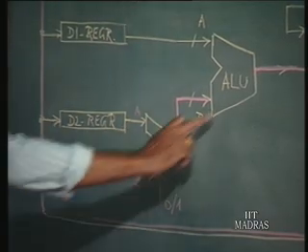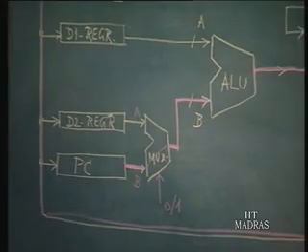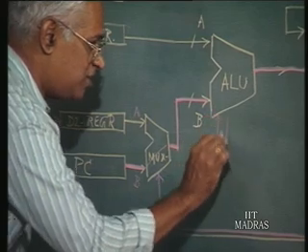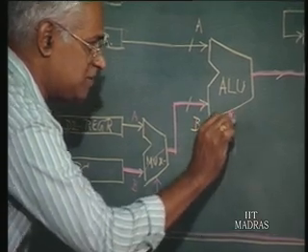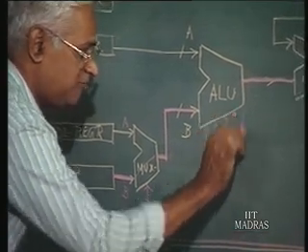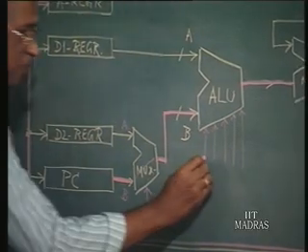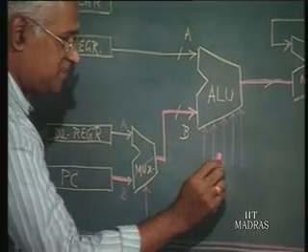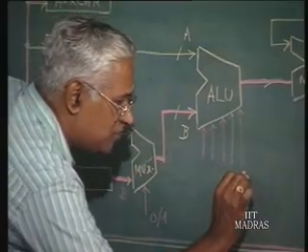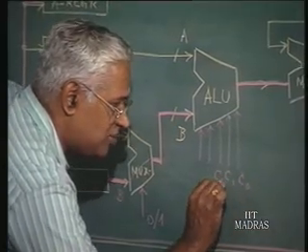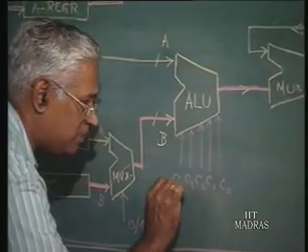Now similarly here the ALU, we will assume the same old 32 function ALU, in which case there will be 5 control inputs, right, a 5-bit code basically. I'll just call this particular code C0, C1, C2, C3, C4, that's a 5-bit code.